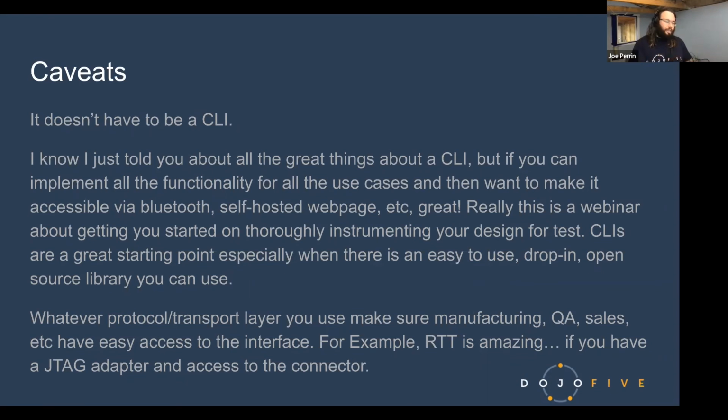Because for that hardware engineer sitting at his desk, it's going to be a lot easier for him to type on PuTTY or Tera Term than maybe he would even feel running a Python script. So if you take anything away from this, instrument your code really well for test, but also expose it with a CLI over whatever protocol transport layer you might be using, and make sure it's one that's easy.